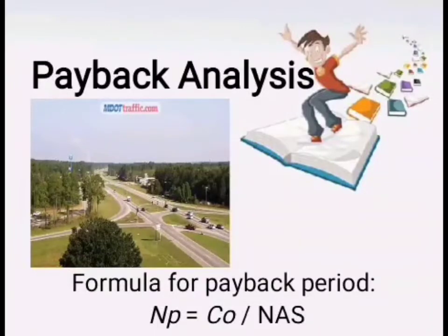Payback analysis is a method useful in evaluating proposals, such as privately funded highway projects. This method delivers an estimate of the length of time taken for the project to recoup its construction cost. The basic formula is NP is equal to CO over NAS, where NP is the payback period, CO is the initial construction cost of the highway project, and NAS is the net annual savings.